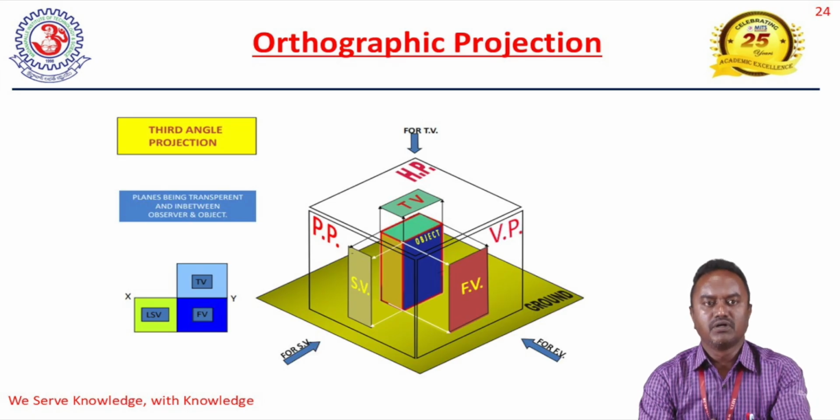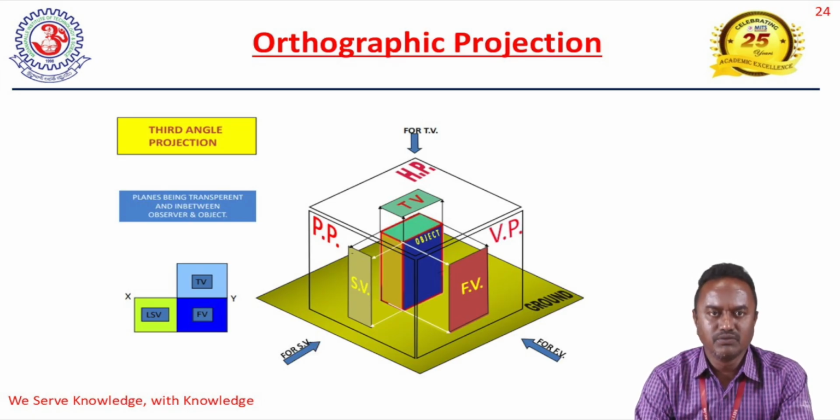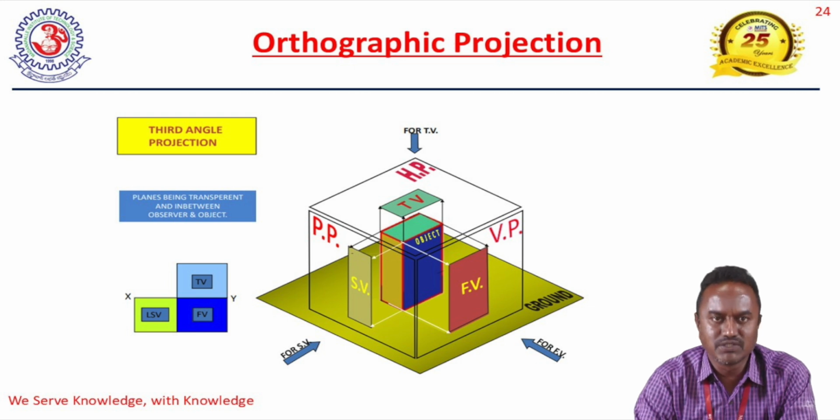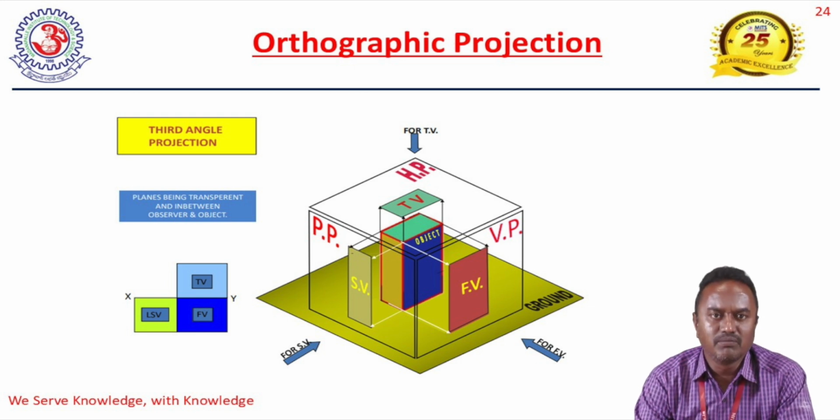So when we come to the orthographic projection, we use the four quadrants theory. The four quadrants theory: first quadrant, second, third quadrant and fourth quadrant. So how can we describe the first quadrant? The first quadrant is normally above HP, above the horizontal plane, and in front of the vertical plane. When any object is placed in the first quadrant, that is called first angle projection.